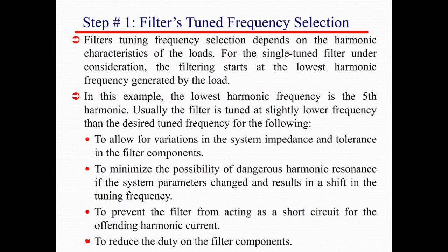So the first step is to do the filter tuned frequency selection. Filter tuning frequency selection depends on the harmonic characteristics of the load. For the single tuned filter under consideration, the filtering starts at the lowest harmonic frequency generated by the load, which is the fifth.